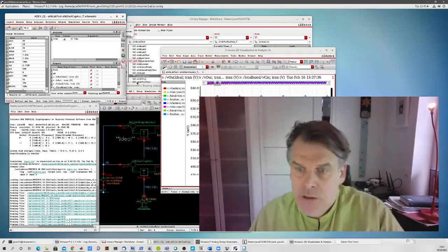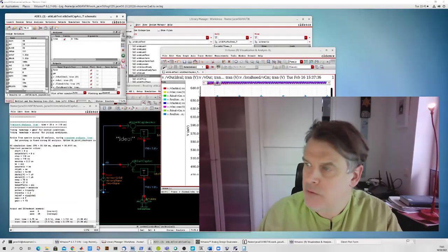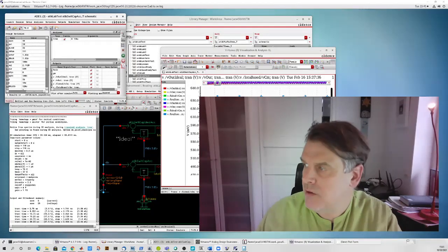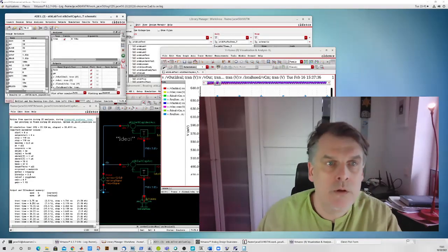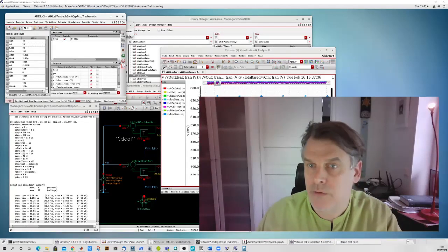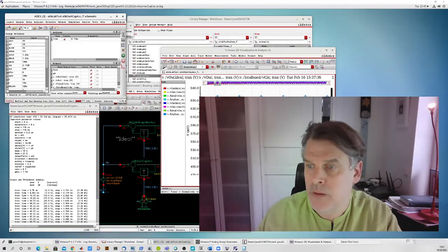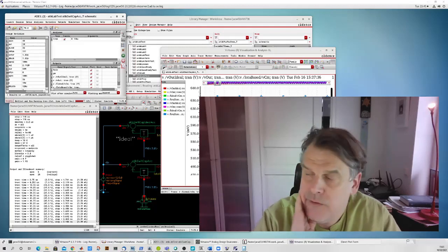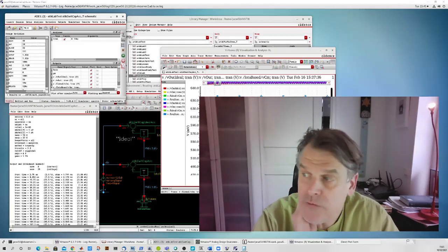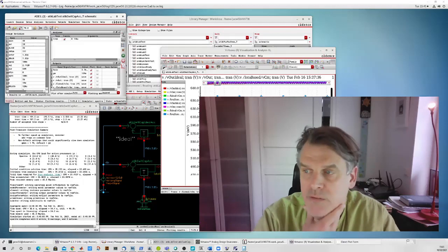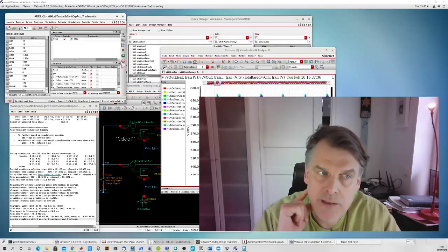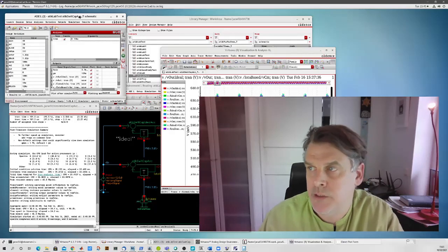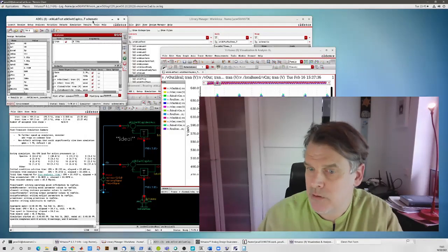Okay. Any comments or questions on this? Some of you are probably quite used to Cadence. I've been working with Cadence since 1994, and I'm pretty used to it. So if you want some tips on how you can do stuff here, please let me know. There is obviously the entire SKILL script language support and Python support for Cadence, which you can invoke and run more extensive tests. You can run ADE XL with different sheets for testing your devices. I haven't really created them for this lab series. It's up to you to test around.